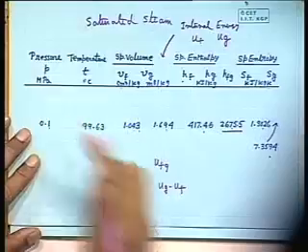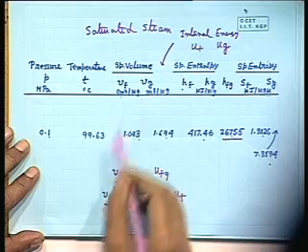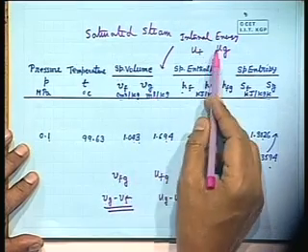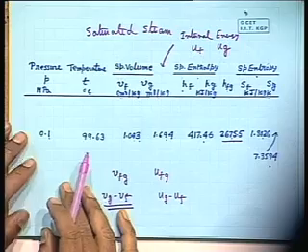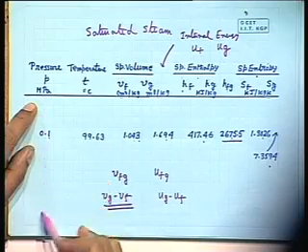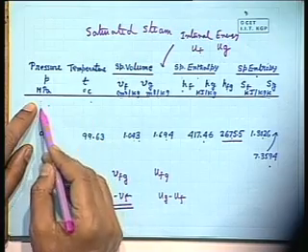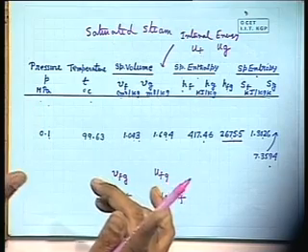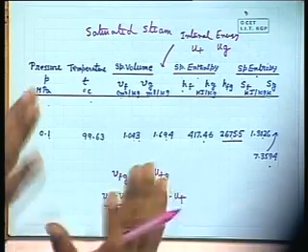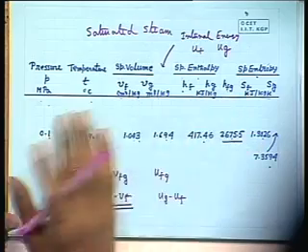Now, this is for saturated steam tables. Again I tell you, in the saturated steam table, with pressure you get the corresponding temperature, specific volume, internal energy, specific enthalpy, specific entropy. These tables are made in two ways. One, pressure-wise with corresponding temperature, another temperature-wise with corresponding pressure. For that, the interpolation job is a little bit easy. You don't have to interpolate much.